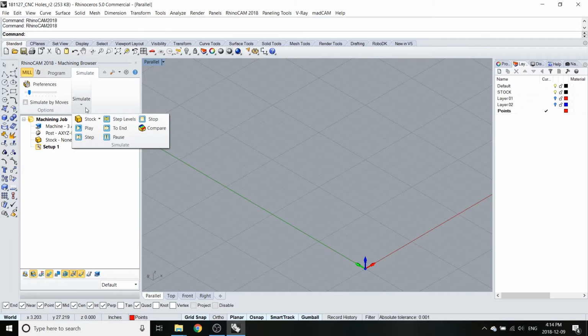It is important for users new to the CNC machine to have their files reviewed by the workshop staff before being executed. Just because no errors emerge from the simulation doesn't mean that the file is perfectly calibrated to the CNC machine. Be sure that the software is set to mill, as this toggle contains the relevant commands to be used by the 3-axis CNC machine. It can be found in the top left portion of the window.